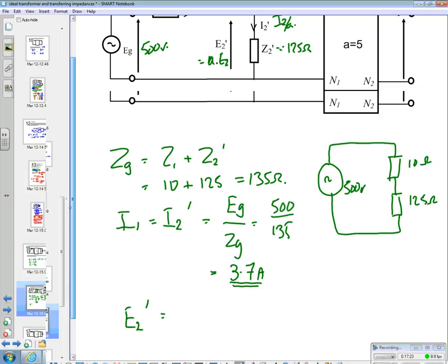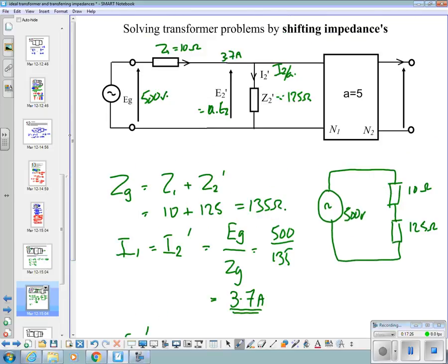We're interested in this voltage being dropped across that impedance, which is the secondary impedance reflected to the primary. Yeah. So if we can find this voltage here, we can reflect it back onto the primary with that formula, can't we? We've reflected it that way by multiplying by A. We divide by A, we can put it back over the other side.